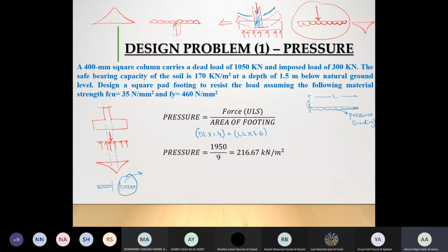And if you remember when I talked about ultimate limit state and serviceability limit state, I told you whenever we talk about the design of reinforcement, we are always referring to ultimate limit state. Always we are multiplying by a factor of safety. In case of any added loads, my reinforcement should be able to take that loading. But when we talk about deflection, we are talking only about the existing load.